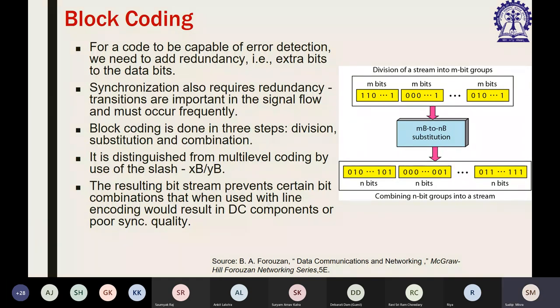So far what you have learned, the line encoding schemes, basically help you to convert the digital data into digital signals. So you have learned the unipolar schemes, for example unipolar NRZ, non-return to zero. Then you also have the polar schemes, polar NRZ, then polar RZ, return to zero. Among polar schemes, what are the other polar schemes? Can somebody tell me? The biphase schemes, Manchester and differential Manchester. Then you have the bipolar schemes, AMI and pseudo-ternary.